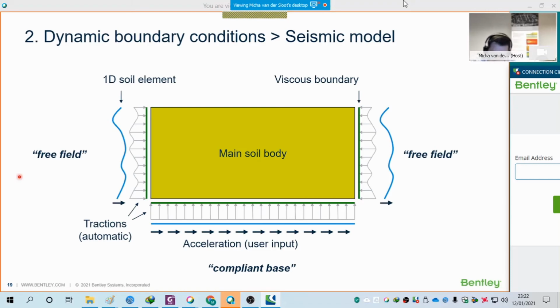So in the latest Plaxis version, or actually it's already there for I think a year now, we have an option. In early versions, you can just use dynamic analysis, and then either the material will be fully drained or fully undrained. So it will either not generate excess pore pressure, or it would be considered completely undrained, so no volume change possible.